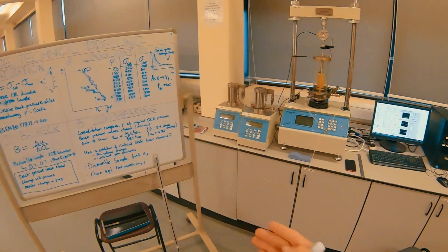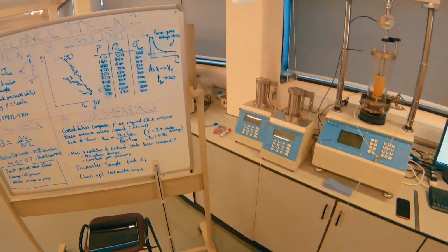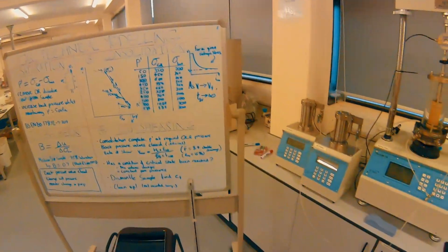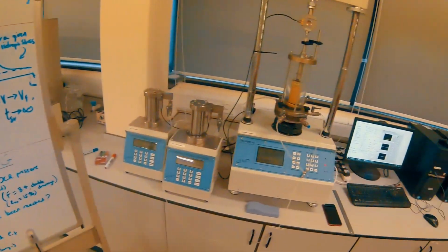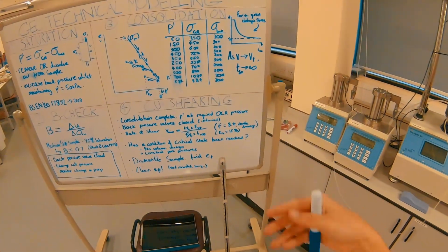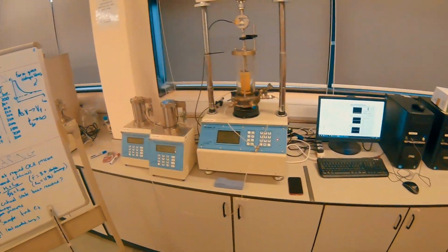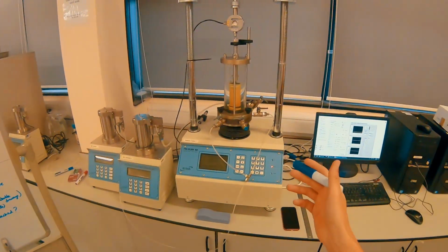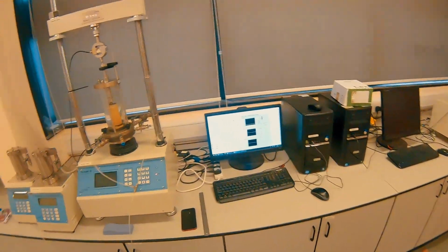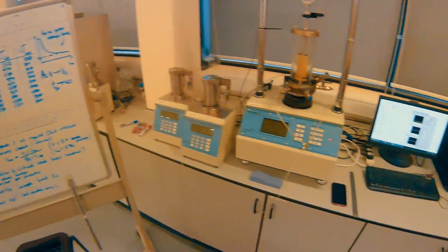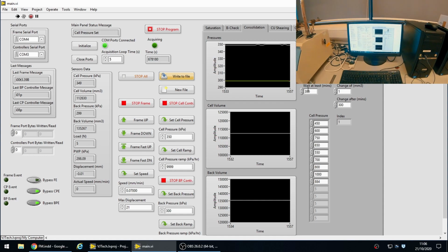That's not technically allowed within the standards, the international standards for triaxial testing of the strength of soils. However, for our purposes, it works pretty well. We know from last year's experience that T100, or the time where we have very small volume changes, approaches 9 hours. And that was with a pure kaolin sample. For our purposes, where we have silty sand in the mix, we're going to reduce that to 5 hours.